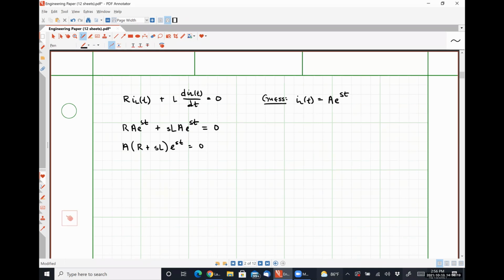So under what conditions would this equation equal 0? There's one that's very, very obvious: A is equal to 0. What A is equal to 0 represents is that there was never a voltage or current flowing through the system at all. So effectively, we never charged or discharged our capacitor. That only works if IS happens to be 0. It's a trivial solution, okay? It doesn't really tell us any information about how this thing behaves, because effectively we're saying the whole system was off the entire time, right? So we've got to get a little bit more creative than that, unfortunately.